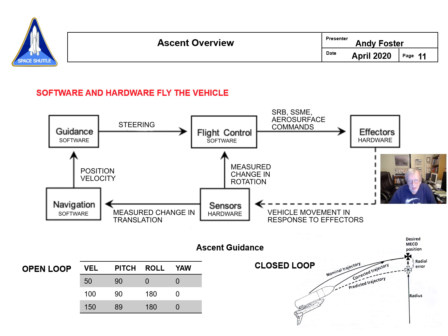And part of the reason that you have these two schemes has to do with the fact that we had boosters, for one thing, that you can't really throttle, and then tons of thrust in first stage, and then less thrust in second stage, and more fine control because the engines could be throttled and they could be moved a little more finely and all that. And in fact, early on in boost stage, you're just trying to essentially loft quickly to get the aerodynamic forces down and then turn it downrange to start picking up velocity and minimize gravity losses. And that doesn't take a whole lot of smarts, really. But closed loop does, because then you've got to get to this very precise orbital target.